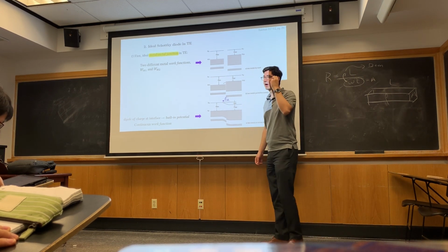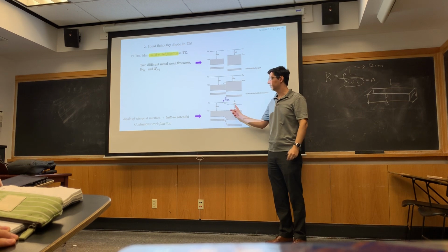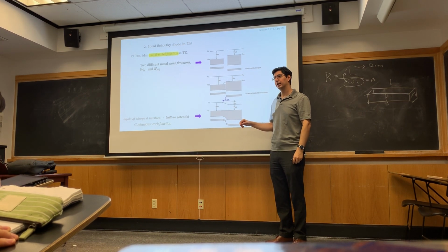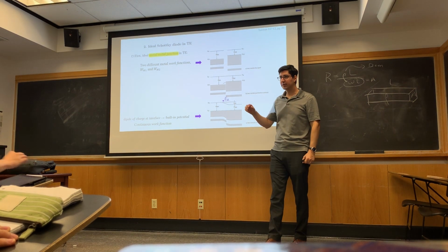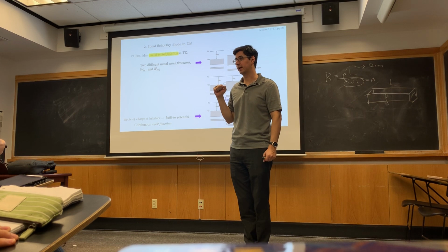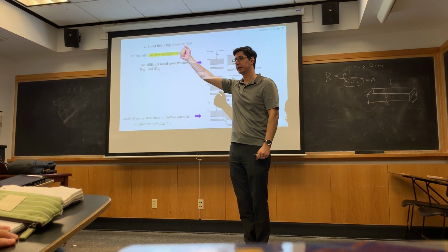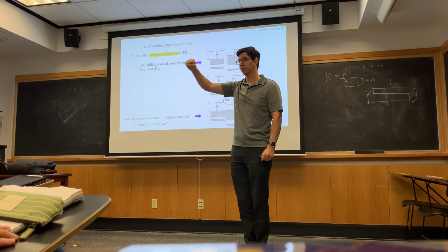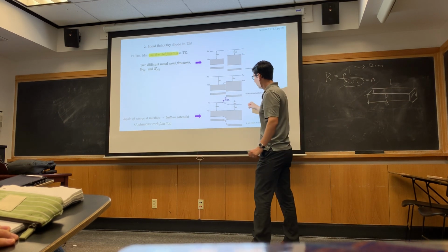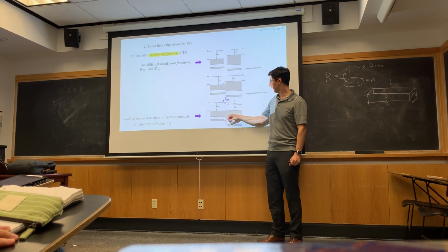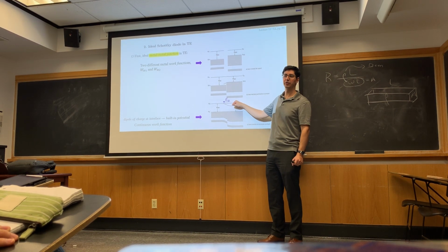Now, I discussed the local vacuum level before. The local vacuum level is, I'm taking an electron out of my semiconductor and putting it right at the surface of my device. I'm not moving it infinitely far away. I'm just pulling out that electron and putting it right on the surface. So there's a dipole here.